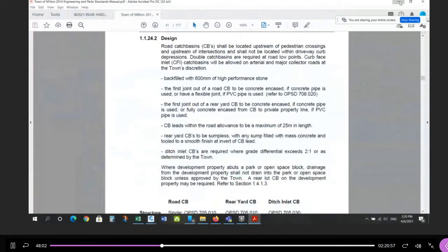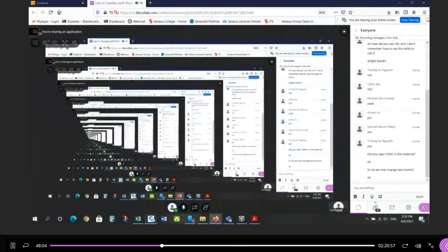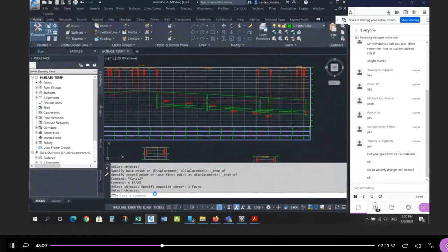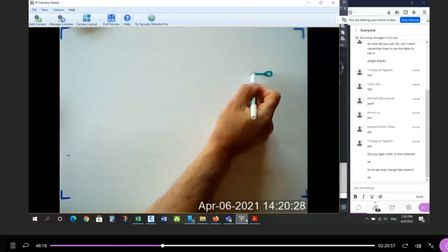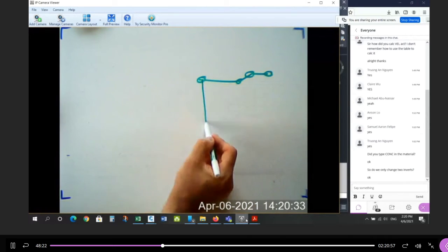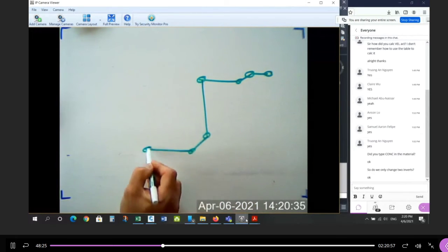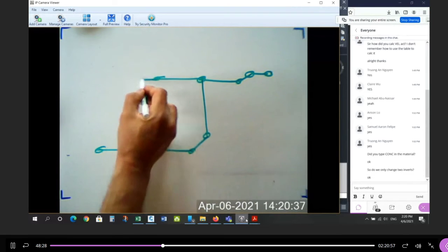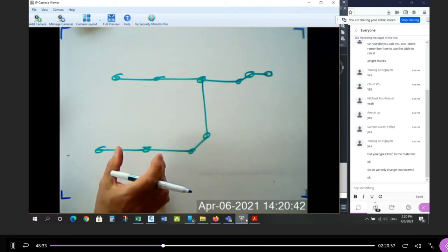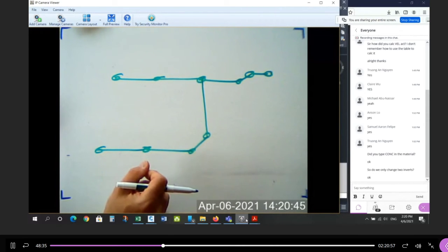Okay, and I deliberately rolled it out a little bit at a time, right? Start with the standard, 0.5%. So you're designing the storm from the bottom up, right? Let's just do this one concept here. The storm is being designed. The existing pipe is here. There's the 825. Then there's the shift. Then there's street A and B. We're coming down here. One more here, and then two more up here. So that's the system. We design them all parallel to the street. The street is 0.5%. These pipes are all 0.5%, which is the minimum allowed.